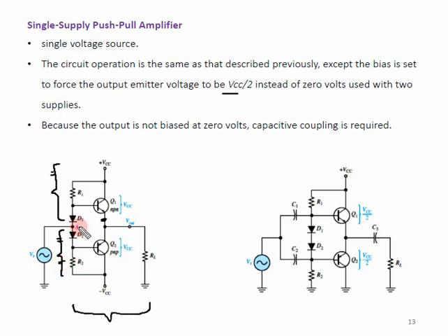So we proved that at this point, because of the value of VCC, R1 and D1, which is the same as minus VCC, R2 and D2, this forces the voltage at this point, which is point A, to be equal to 0. So VA is equal to 0. Now the property of this circuit is that it would transform this voltage at this point, which is your emitter point. If I draw something like this, this is an emitter, and this is your RL resistor, which is grounded. From here to here, this is VE.